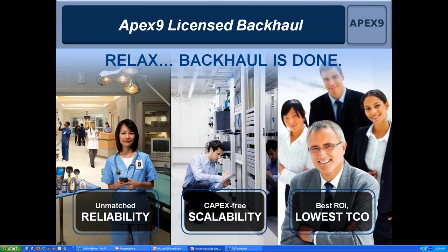Another question. If I deploy a 6 gigahertz link with 3-foot dishes, can another operator deploy another 6 gigahertz link with 4-foot dishes and force me to upgrade my dish size to not create interference? The answer is kind of. So under existing rules, and that's what's being discussed, if you remember, on the NPRM, the Notice of Proposed Rulemaking slide, talking about not having to upgrade your dish size.